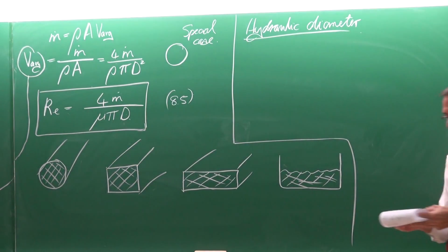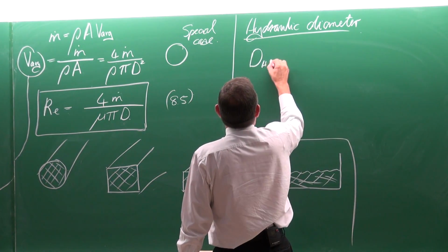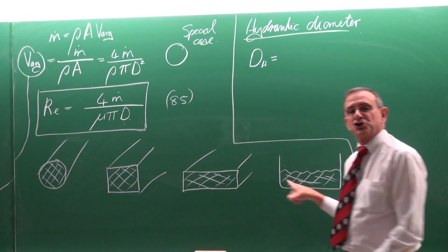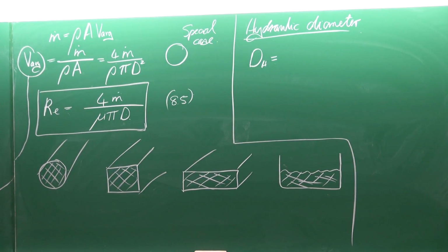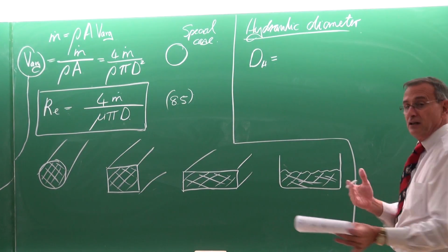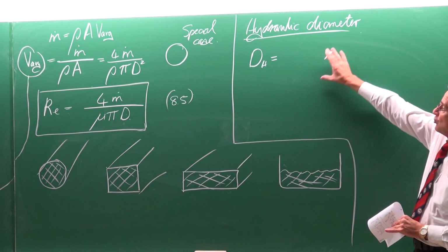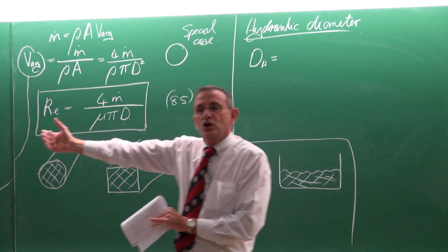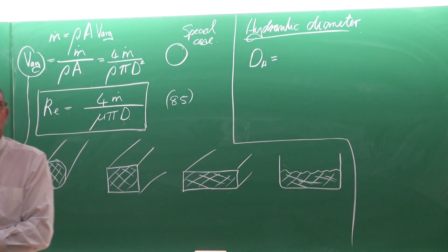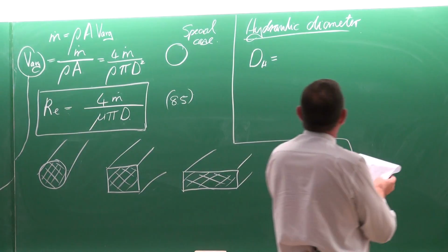The very simple explanation of the hydraulic diameter is that anything that's not circular or round, you're going to make as if it is round. And you've done it in fluid mechanics. So for any geometry like this, by using the hydraulic diameter, you can from there on use all the empirical information that you can get in textbooks as if it is a circular tube. So that is what you can do with the hydraulic diameter.